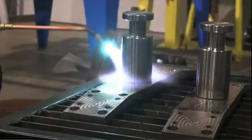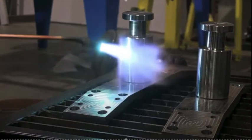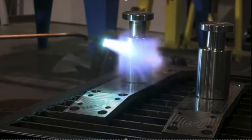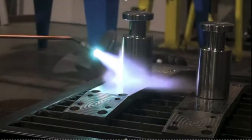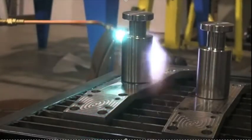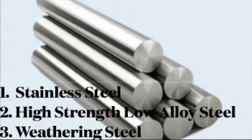Next kind of steel, alloy steel. Carbon steel to which various elements such as chromium, cobalt, copper, manganese, molybdenum, nickel, tungsten, or vanadium have been added in sufficient amount to obtain particular physical or chemical properties. Kinds of alloy steel. First, stainless steel. An alloy containing a minimum of 12% chromium, sometimes with nickel, manganese, or molybdenum as additional alloying elements.